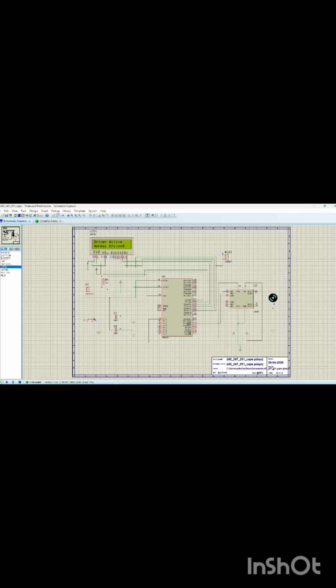Next is the hardware phase. We built a prototype using 8051 board, IR sensor, a small DC motor setup and buzzer. We observed that when a hand was placed near the IR sensor, the microcontroller interpreted it correctly and controlled motor direction. When a hand was absent for a set time of 3 to 5 seconds, the buzzer was triggered, effectively warning the driver. This shows our design was functional and reliable.